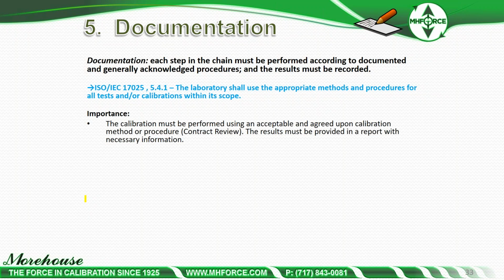The worst thing you could tell somebody is calibrate to manufacturer specifications, because no one knows what that really means. Does that mean I should be monitoring linearity? Should I be looking at repeatability? Should I be looking at temperature creep? Manufacturer specifications, if you were to do all the calibrations on their spec sheet, it would cost an absolute fortune to verify them. It's just not practical.